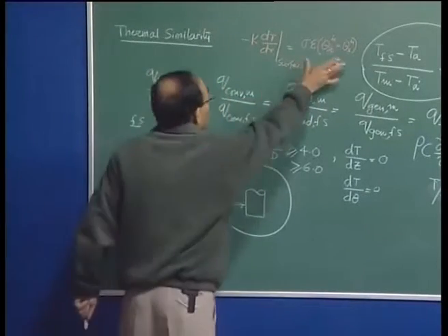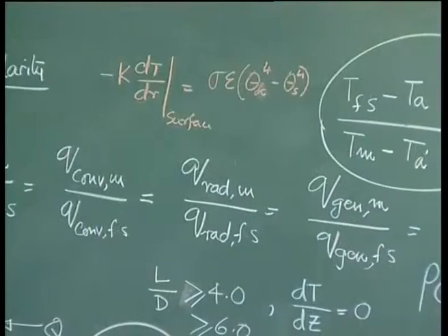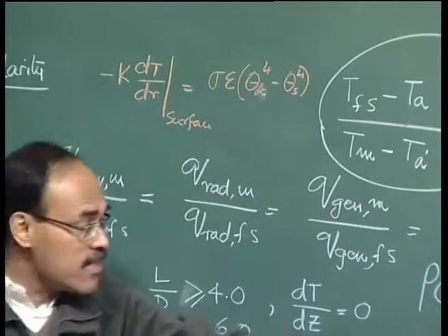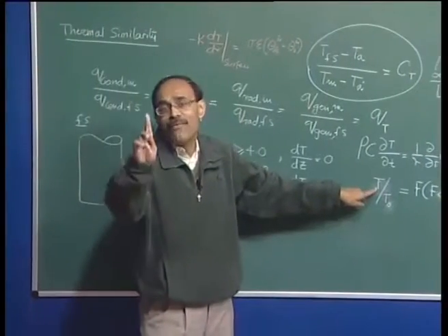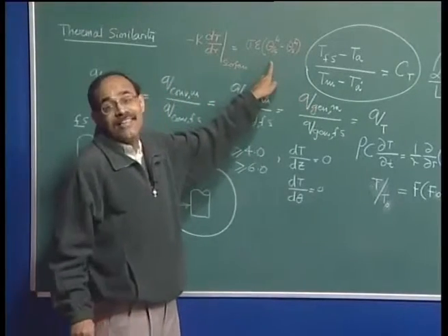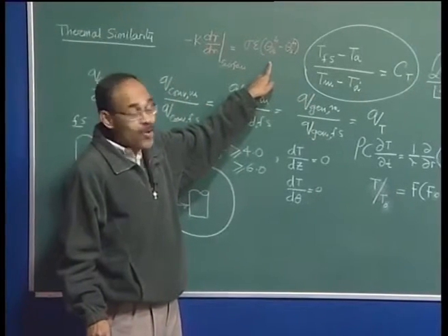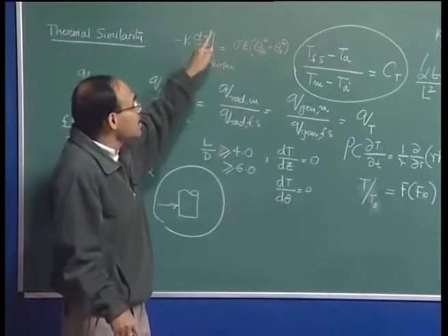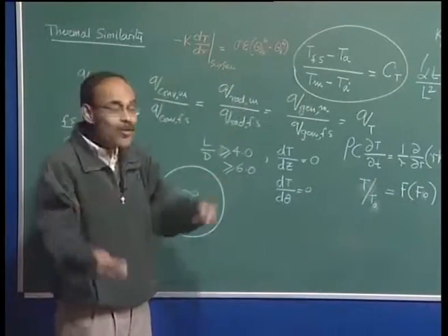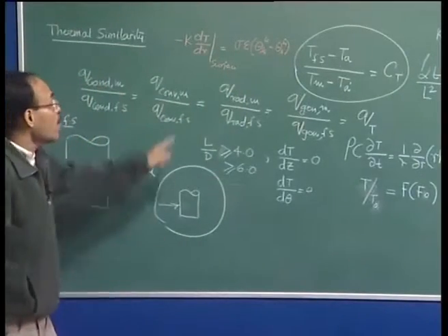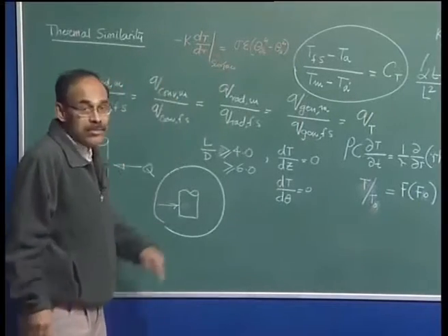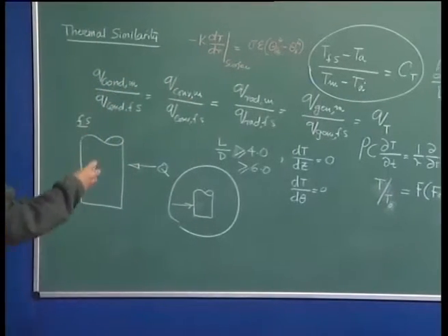So, this is the radiation flux, and this is the heat flux which is being received at the surface itself. These thetas and T's are one and the same thing, only difference is this theta is in absolute scale. So, it is 273 degrees plus T infinity, that is equal to theta infinity, that is the only difference. Now, from this number also we can get a boundary condition.